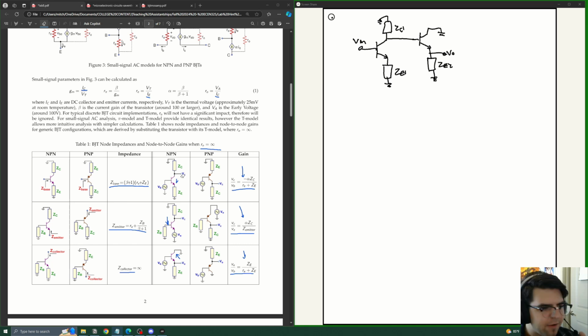And then since we have the values of what the gains are, we can simplify the analysis with the idea of two-port modeling. So the BJT amplifiers, we've got one input going in, and they lead to one output, where the relationship between these two is the gain. So we can model these things just like with the op amps. You can write a little amplifier symbol, which usually looks like a triangle, and then we can just assign the gain of the configuration there.